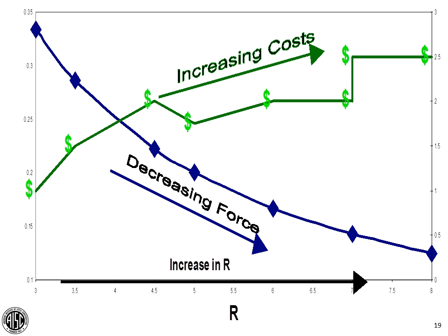One is you're always permitted to remove backing. So if you choose that as a better option for some reason than leaving the backing and providing the fillet, that's okay as well. I think that'd be unusual to do. The other thing, in our review session, somebody brought up the fact that people get confused about removing backing sometimes because they confuse backing with weld tabs, like run-out tabs on the edges of CJP welds. Those are very different things. So even when you have to remove a tab, you could still potentially leave the backing in place.